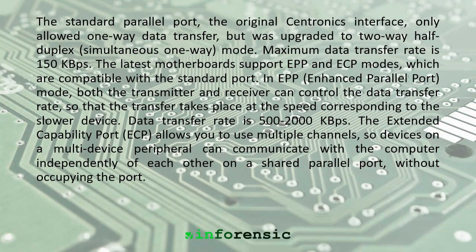The standard parallel port, the original Centronics interface, only allowed one-way data transfer but was upgraded to two-way half-duplex, simultaneous one-way mode. Maximum data transfer rate is 150 kbps. The latest motherboards support EPP and ECP modes, which are compatible with the standard port.